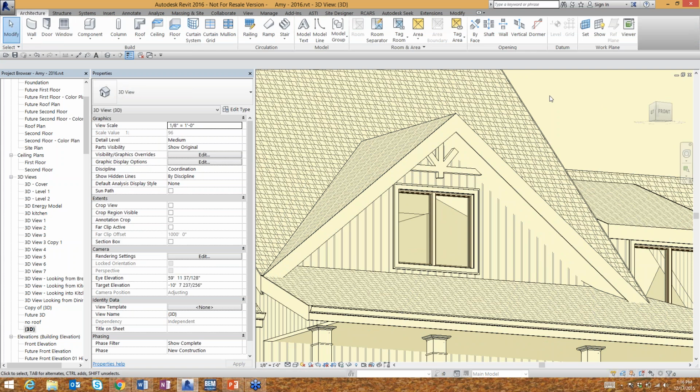It could be something added to expose the rafters, or if you actually have 3D members for the trusses or rafters, they're going to be visible, and we can draw the members in. I haven't done it in this project. This project just includes the members in the thickness of the roof, so we don't see them. But we could make the roof smaller and draw the framing members that would be exposed. It's a different approach, but I think you could do it. I just didn't take that approach on this project.